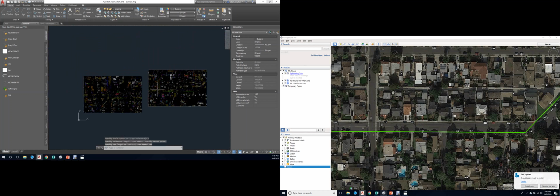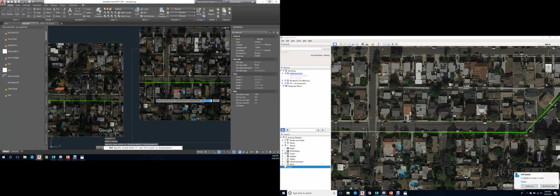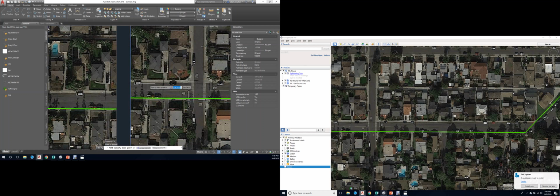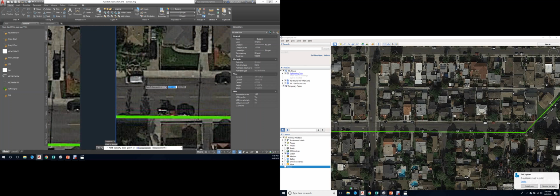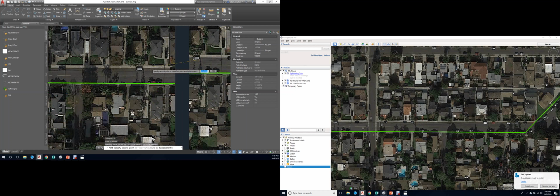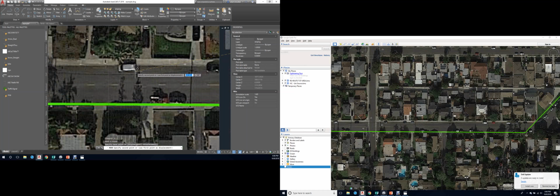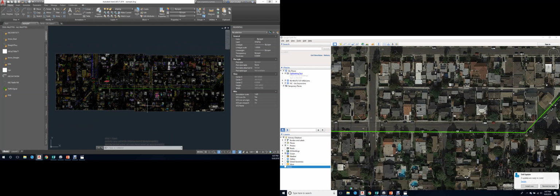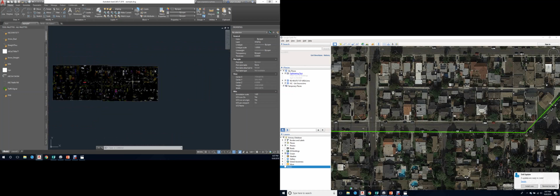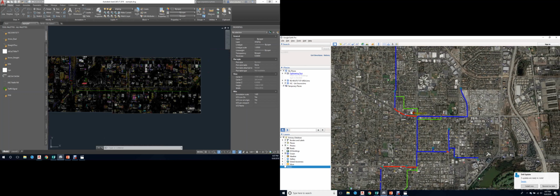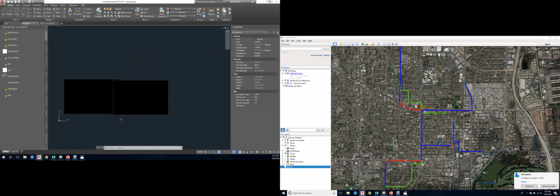All right, now you have two to-scale screenshots. So all you do here is select a reference point and select this van right here. Move this over to a matching reference point on the other screenshot. Bam. And now you have two screenshots and more of your work area covered. So you can imagine you have a ton of screenshots for a file this size. For now we'll just work over here with two.